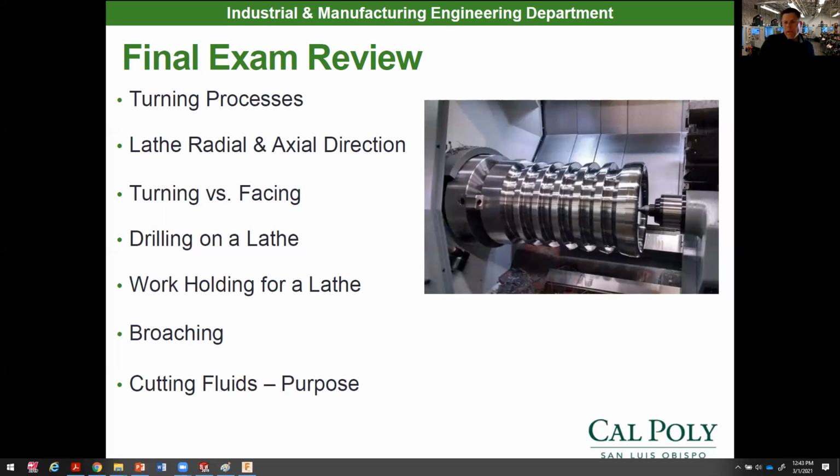Then we learned about many different types of work holding on these lathes as well. Work holding can basically be a 3-jaw chuck, which is the most universal work holding on a lathe, or it could be a collet chuck or a specialty fixture if you really had that, or soft jaws. But I would know the most prevalent work holding for a lathe, and that's a 3-jaw chuck. So this one you're going to see around the most likely. Now, for a manual lathe.